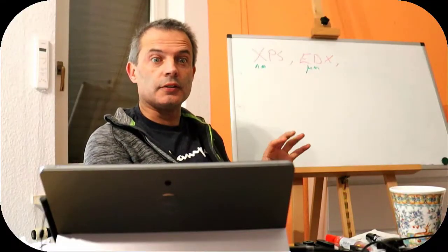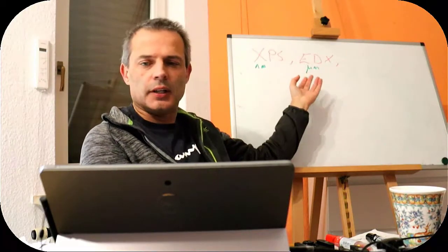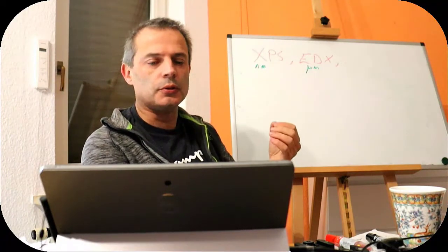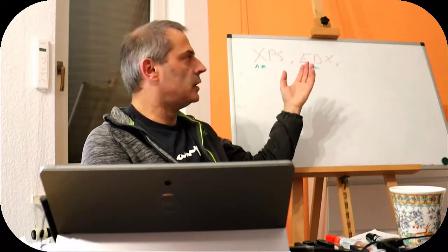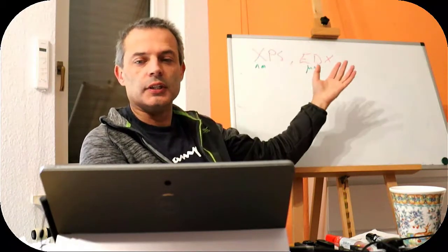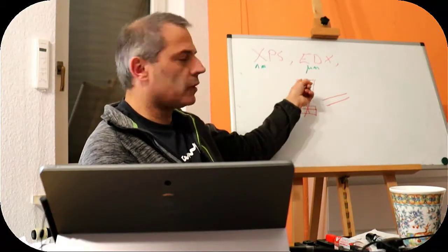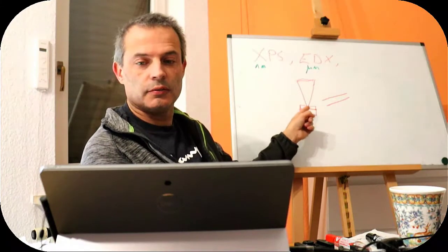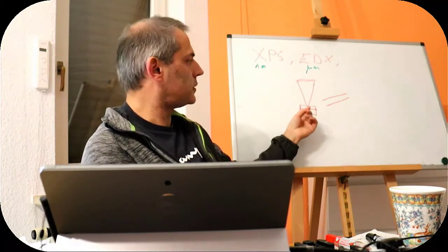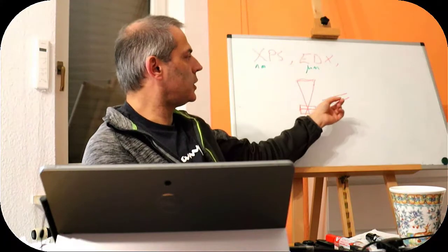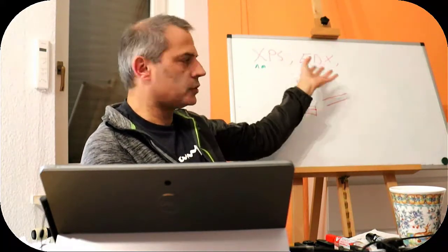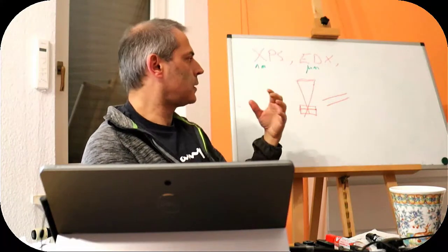Getting on to the technicalities of how this is actually measured, let's have a look at EDX first. But the problems that we will see will be due to the problems of analyzing the energy of electrons and of dealing with X-rays. So here we have what would be our electron beam in the sample chamber, crossing over as a focal point, not necessarily at the surface of our sample. And we have some kind of takeoff for our X-rays, and the rest of the chamber is metallic.